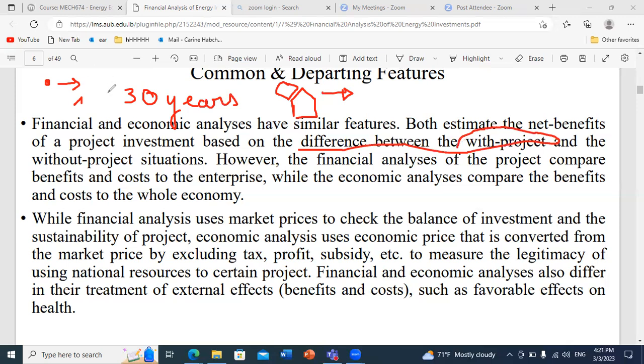Of course, I have the investment, I have the maintenance, etc. But I can get rid of my electrical bill. So I can compare with the without project situation, when I should pay my electrical bill each month. So now I can compare for each year what the savings are, and I can do the economical analysis over the whole lifetime of my system to determine my payback period. So at what time I can consider that I already paid back everything and I will start now to gain money.